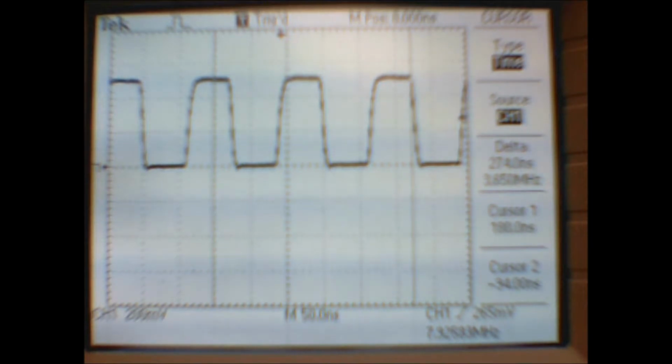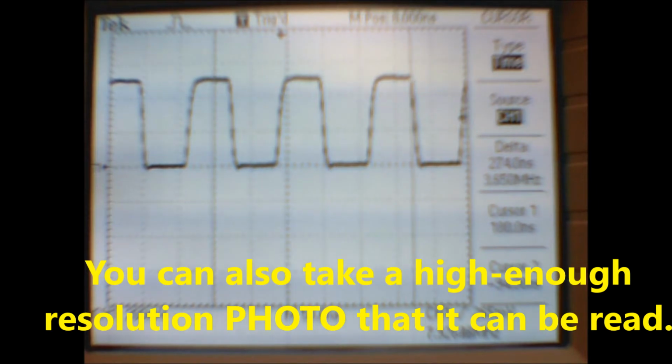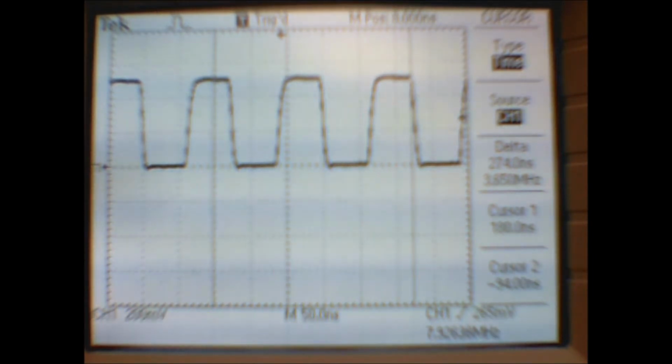And with all waveforms that you measure in this lab, remember that you need to record the scope trace in your logbook. So either that means that you draw it by hand on graph paper to scale with labeled axes, or, and this is probably the better option, these oscilloscopes allow you to save the image onto a data stick, and then you can move it over to one of the lab computers and print out the image. But either way, you have to get an accurate representation of what you see on the screen into your logbook, and that's true anytime you look at a waveform on the oscilloscope screen.